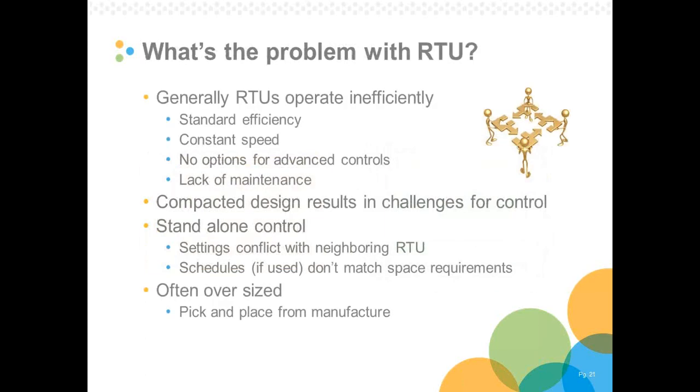So what's the problems with RTUs? RTUs generally operate inefficiently. They are standard efficiency from the factory in both the heating and cooling. They are typically constant speed. There's really no options for advanced controls.